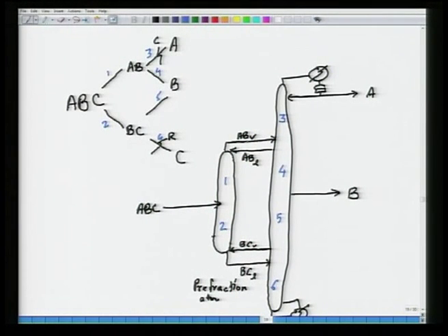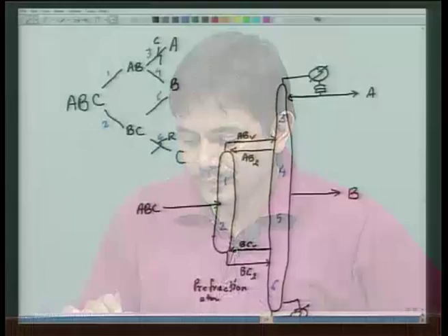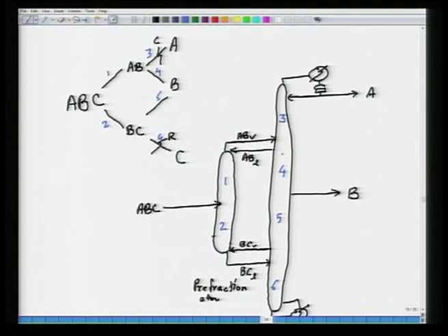How is this different from what we have here? The vapor between the first column, the pre-fractionator, and the second column, here the vapor is having to flow from the pre-fractionator to the main tower, through the tall tower. At the bottoms, the vapor is flowing from the tall tower to the pre-fractionator. The direction of flow of the vapor is in opposite directions. So, if I have the column, the pre-fractionator, at a high pressure, the top stream will flow naturally into the main tower.